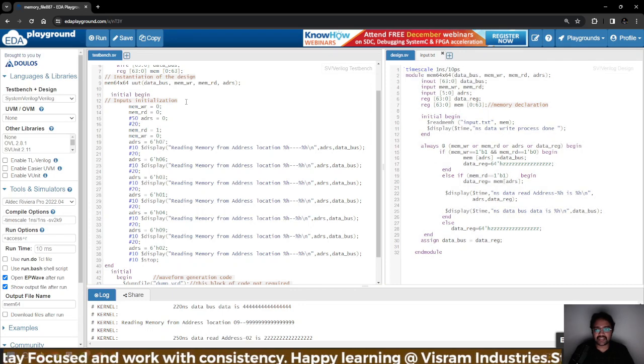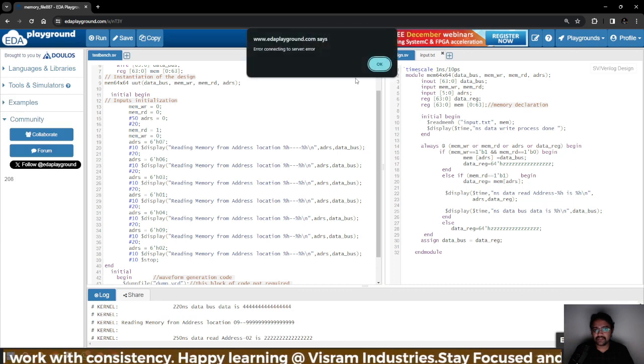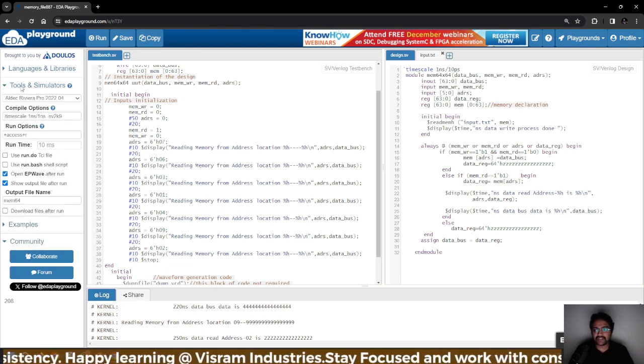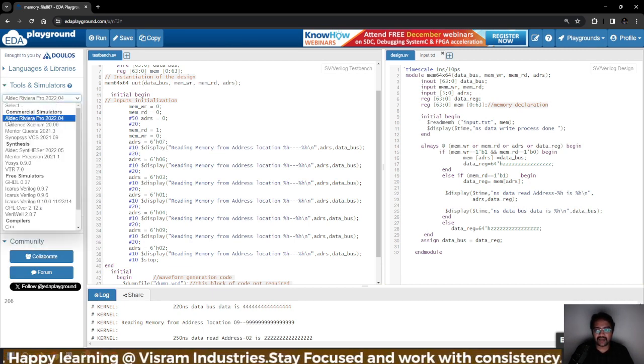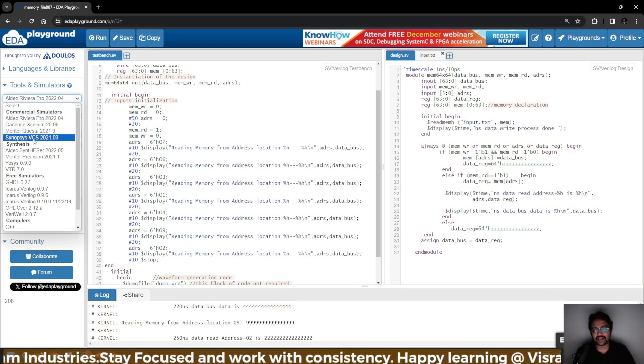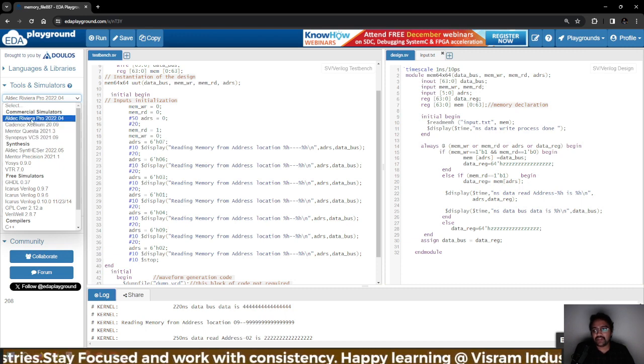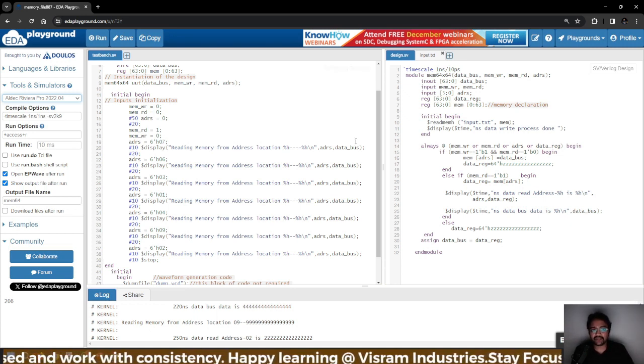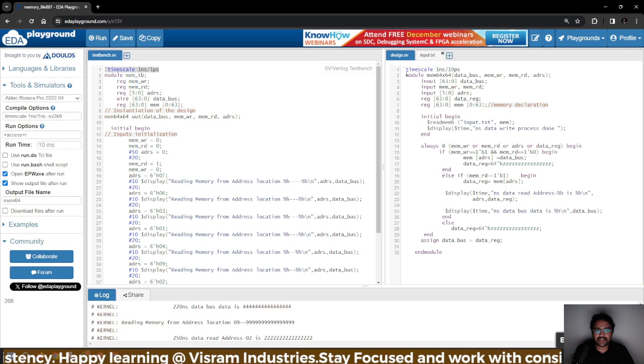After making the design and test bench, save it first, and by saving, you can see the EDA Playground with tools on the left side, and you can see the tools and simulator. Select Aldec Riviera Pro. This is one of the leading vendors for simulators, and this is an online simulator that we can use. Synopsys is another company for simulations, and we are using Aldec now. Libraries will be internally linked. We are not mentioning any libraries as we do in VHDL. And the time scale we have given as 1 nanosecond.